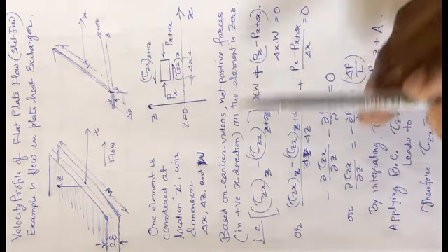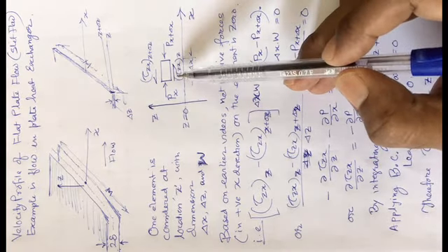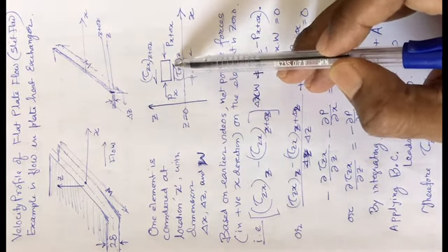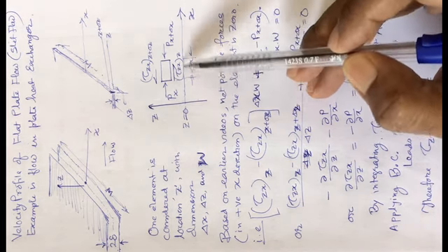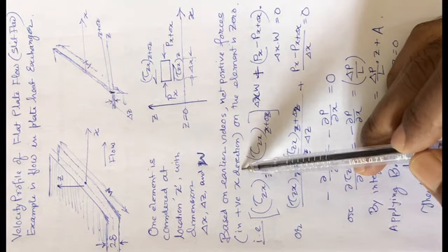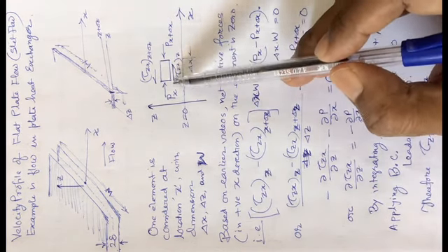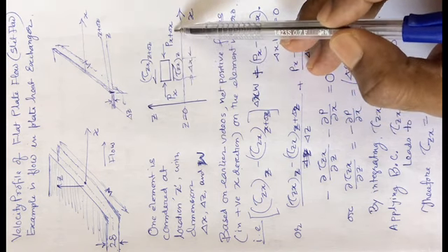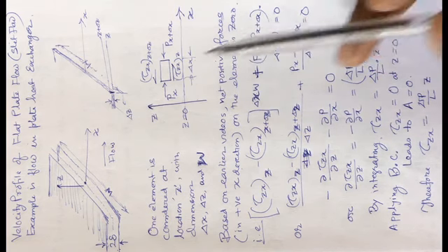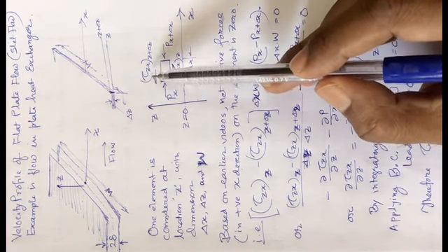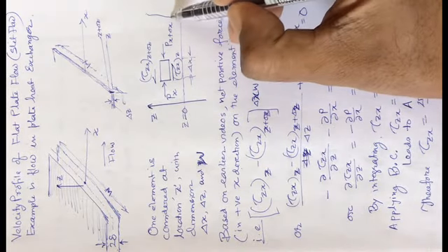Now the net positive forces acting in the positive x direction here will be near to the maximum velocity. So here maximum velocity occurs at location z equal to 0. So in the positive z direction here, positive shear stress will be acting in this direction, and at location z plus delta z it will be acting in the opposite direction, because we are expecting that the velocity profile will be like this.